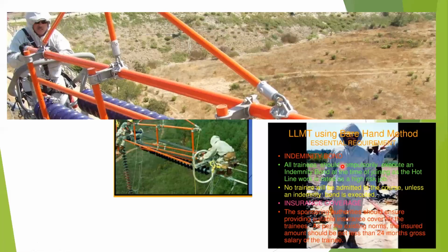And all these are, guess whether this is an insulated or conductive kit. It's a conductive kit, right? You go and get over here, and this kit has a clip. That clip can be connected to the conductor. Then your potential comes up to 400 kV or 220 kV or whatever.